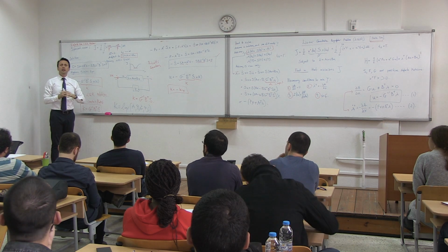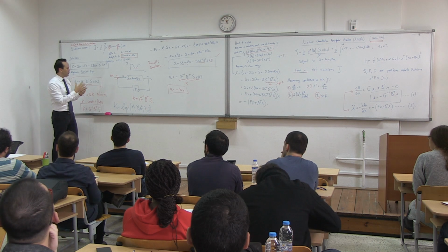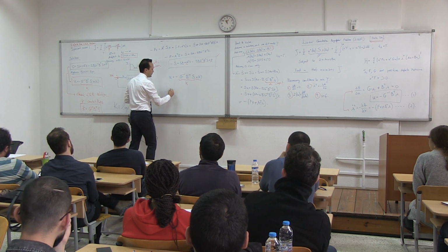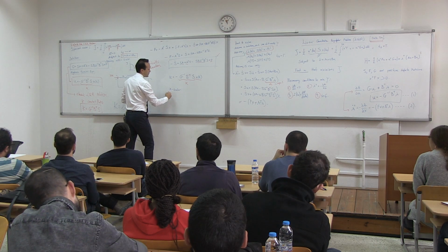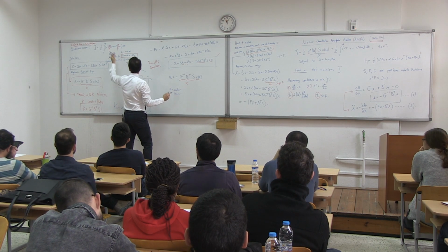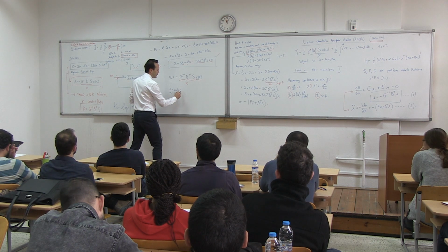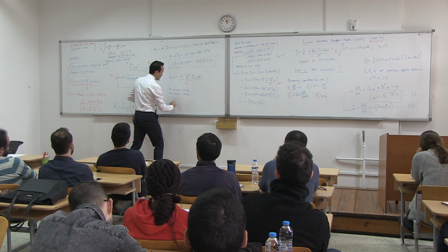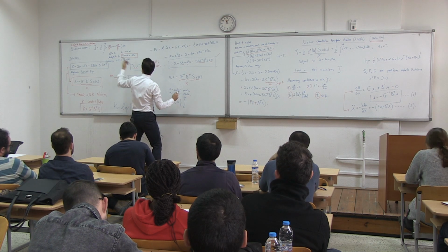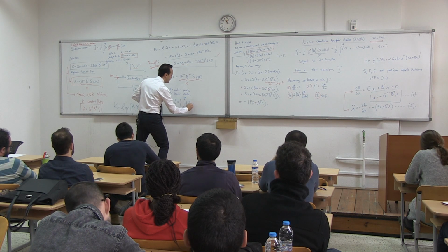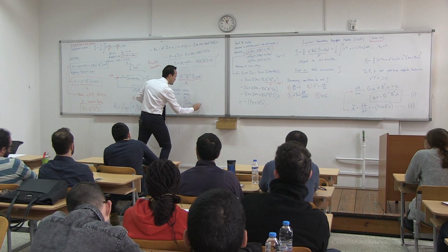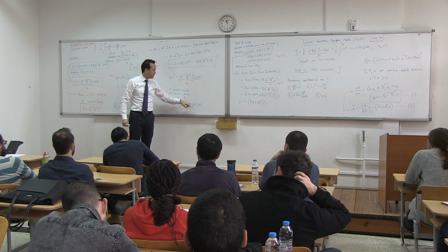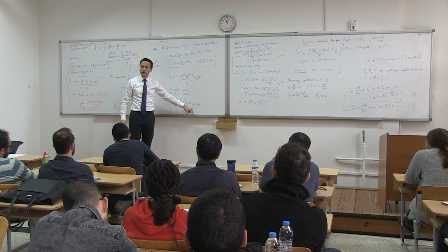If F was a large number and G was a small number, and when I say number, of course, these are matrices, but maybe to simplify the problem, let's think first that x is a scalar, and let's think u is a scalar. In which case, F and G would also be scalar numbers. So this would look like this: J is equal to 1 over 2, integral from 0 to infinity, it would simply be F times x squared plus G times u squared times dt. Okay, let's think of this first as one-dimensional variables and these ones as scalars.